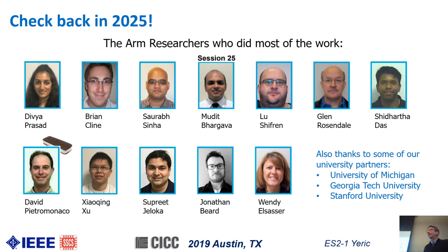You didn't mention negative capacitance. Yeah. It was on purpose. So it's unclear to me if negative capacitance FET is actually usable. I admit I'm not 100% up to date on the literature, but I haven't seen convincing arguments that the negative capacitance effect, which I believe is a ferroelectric effect, can operate at the switching speeds of an actual CMOS node.